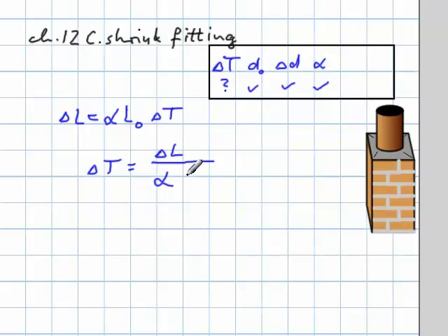And then we also have to divide by the original length, which would be 2.0026 centimeters. Notice that we don't have to convert to meters on this one, because this one is in centimeters, this one is in centimeters, so the two divide out, and the only unit that survives is the reciprocal of Celsius, which is the unit for the alpha, and because it's a reciprocal and this thing is in the denominator, it goes back to the numerator, and we have a typical Celsius degrees here as the unit.